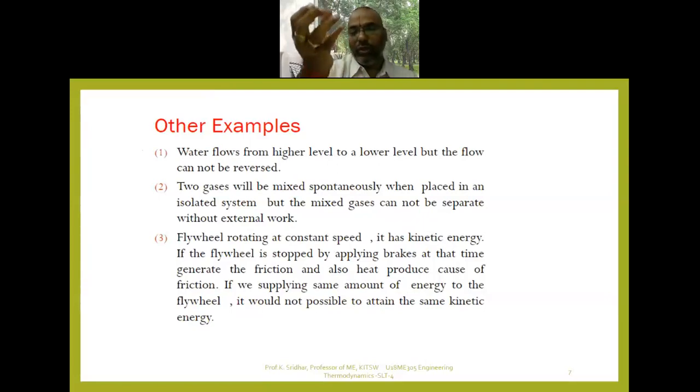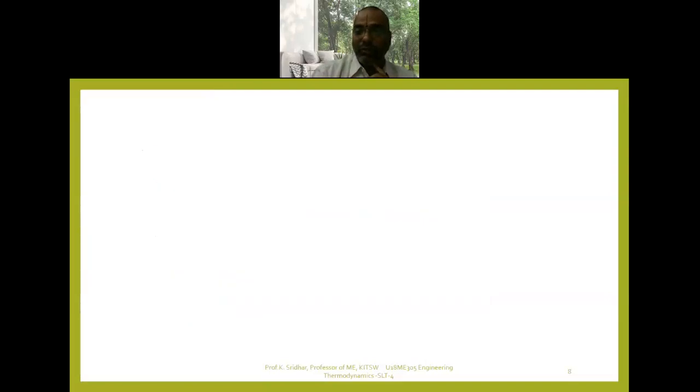From the source, it will take some amount of heat input in the form of Q1. Similarly, there should be some heat rejection, that is, heat rejected to the lower temperature thermal energy reservoir, which is called the sink. So a minimum of two thermal energy reservoirs is required to produce some work output from a heat engine. Only under that condition is the process feasible. With a single thermal energy reservoir, it cannot work. Such limitations are not given by the first law of thermodynamics.